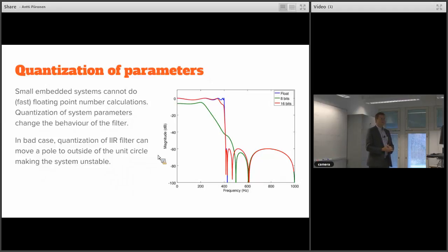If you take just 16-bit accuracy, which is quite nice already, it's lots of decibels. Wait a minute, 12 bits is 70, 16 bits is 96 decibels, right? So 16 bits more or less covers what humans can hear of the differences in sound pressure. So 16 bits would be good for data, but if you start doing this kind of design with 16-bit arithmetic, you start to lose some accuracy. You can see the accuracy lost right here, which means that the 3 dB point is no longer the 3 dB point. So it actually shifts the beginning of the filter.